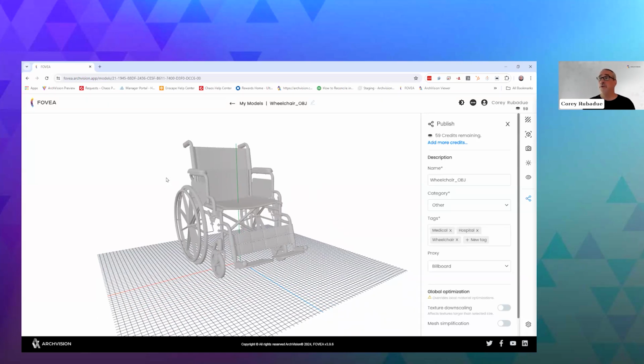If I wanted to remove some nuts and bolts from a highly detailed model, I could select those parts of the mesh and delete them, and work on some pre-optimization of the data sets, which is always good to do if you're trying to get highly detailed models into Enscape and you know that you're going into Enscape. You might want to do some of that pre-optimization early on. Okay.